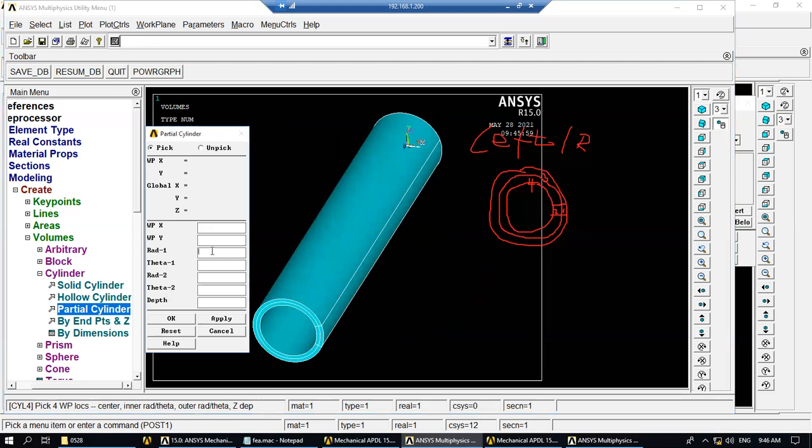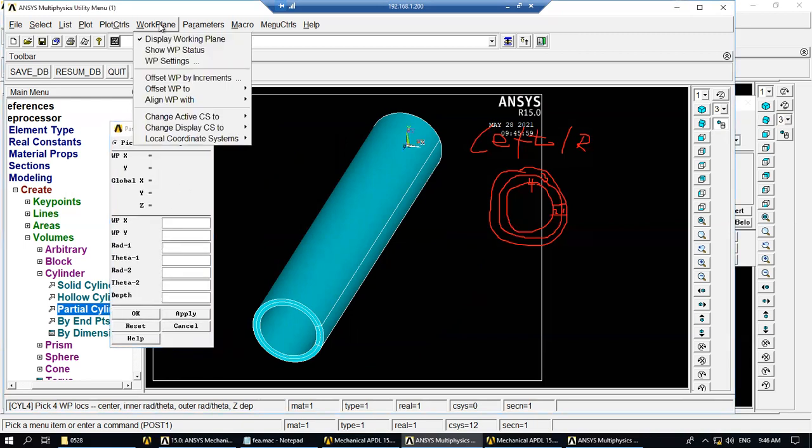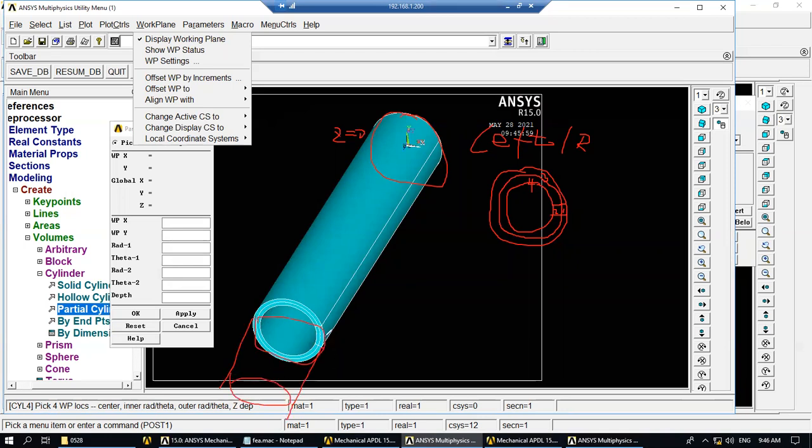So you can do the same thing to the middle part, but in this case you have to move, because now we have this, you see WP, WX. This is the work plane, and you have your work plane at the starting section here, which is Z is 0. But now we are going to model new tubes like this. But with the depths, you don't have Z1 to Z2, you have only a Z, the length. So we have to move the starting point here, the new Z0, let's say.